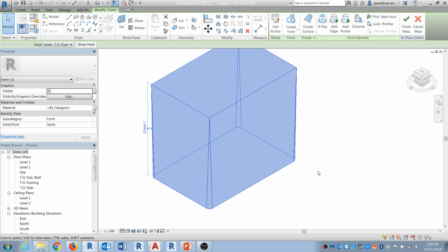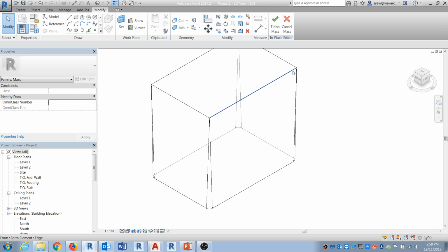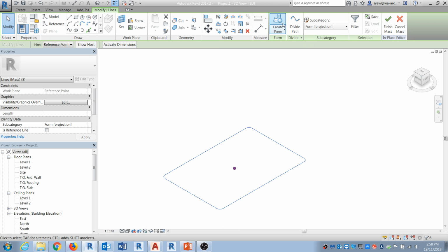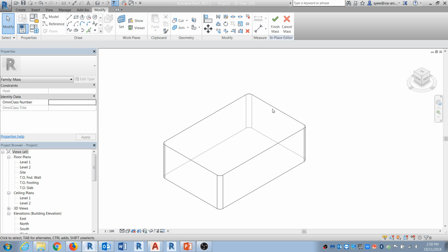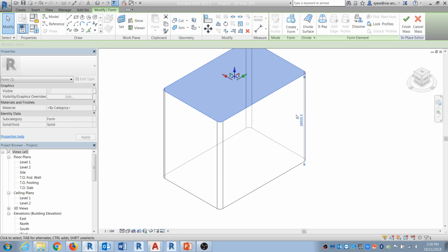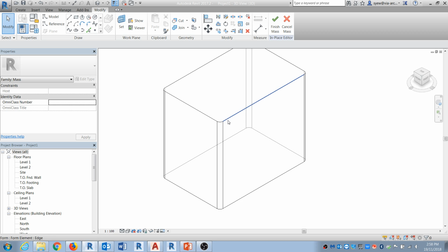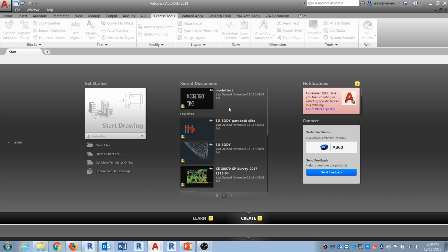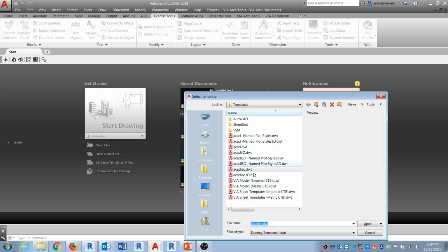Okay, finish that. Now you still have a problem, because the top part is not the same as the bottom. So you have to dissolve again, get rid of this, and extrude it again. For a lot of users, this can be very, very tedious. Now, if you want to do a chamfer this way, it's like, yeah, good luck. So you have to create a different kind of item. So rather than doing that, I'm just going to show you how massing is done inside AutoCAD pretty easily.